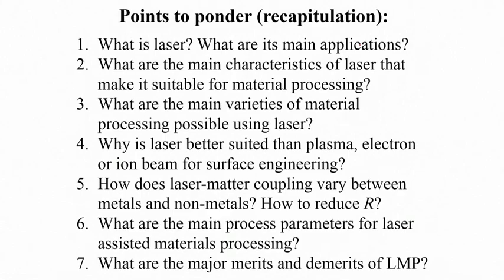So you require the beam to move fast, which is possible. Independently, one can change or increase the speed, but you need surface integration, and you also need to allow sufficient interaction time for the heat to penetrate all the way to the other end. So if you want through and through heating, this is not an ideal tool for bulk heating. You'd rather use a furnace if you have, let's say, a few centimeter cube volume of material. You can't heat the whole material using laser.